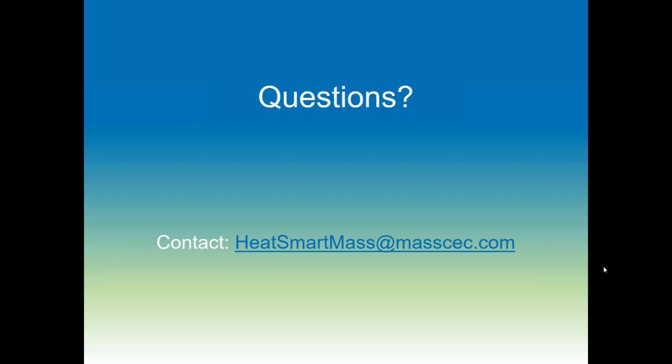And you certainly have a lot of days where it's going to be colder than 30 degrees, and that's, of course, when you need the most heating. So the cold climate heat pumps that qualify for the MITC rebates and other incentive programs have similar requirements. Those units have been vetted to ensure that they will operate efficiently and provide a significant amount of heat in our local climate.